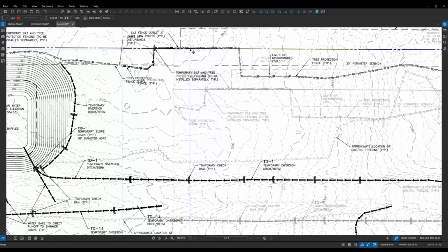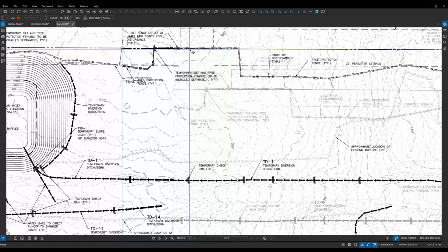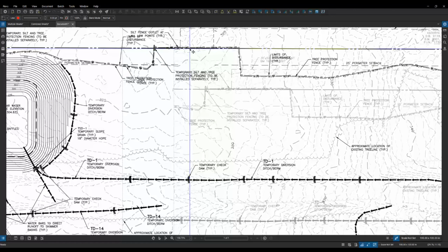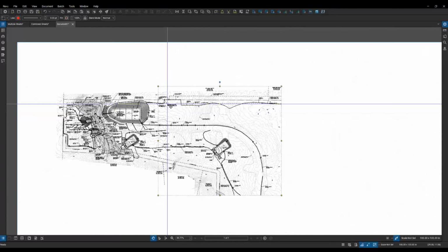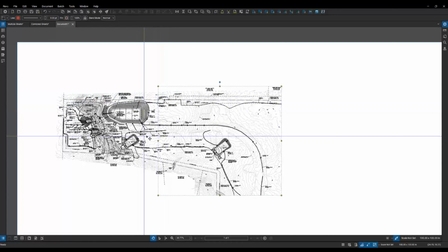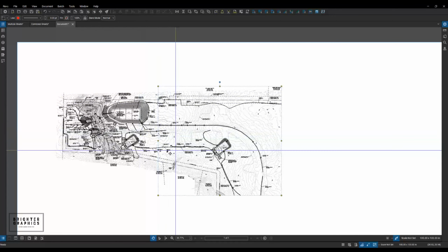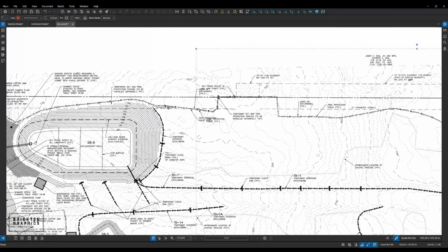And a lot of these contours and things on the document will help us get close to where those line up. And then I'm just going to let go, leave it there. And even though those overlap, you can see the continuation there. So if we do our silt fence again, we can draw a line all the way across these multiple sheets and get the total length of material.